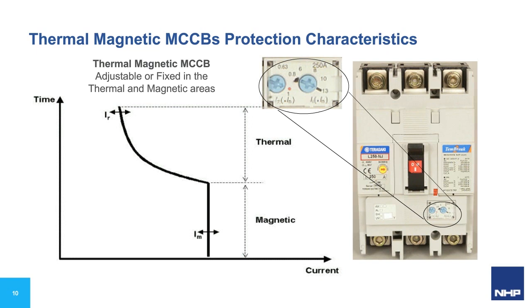In the standard AS/NZS 60947-2, this type of breaker is referred to as Category A. Thermal magnetic breakers are the cost-effective option. Because of their characteristic and limited adjustability, as well as their total reliance on magnetic structure and dynamics, they should not be used upstream of other thermal magnetic molded case circuit breakers if high levels of selectivity are required.